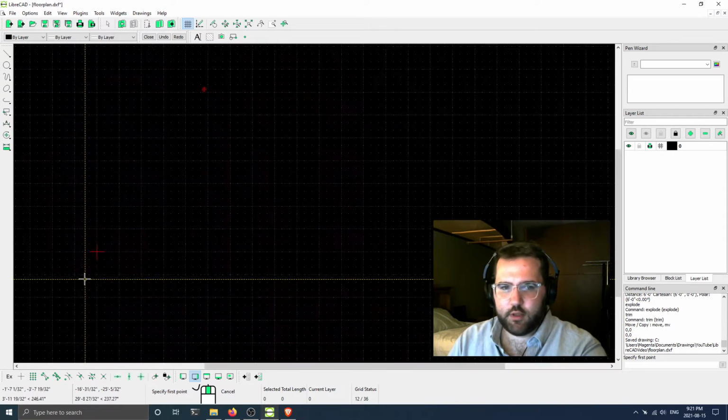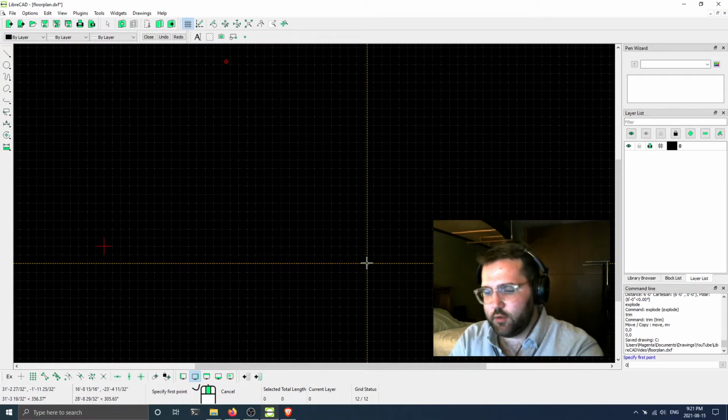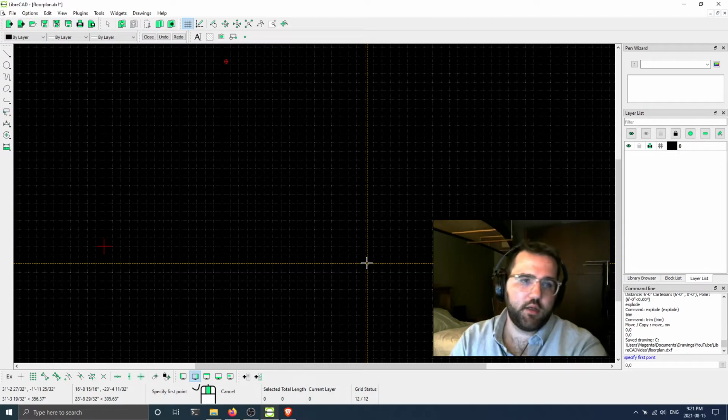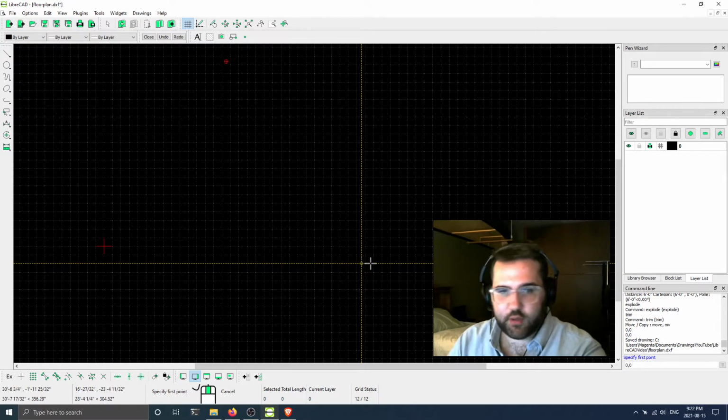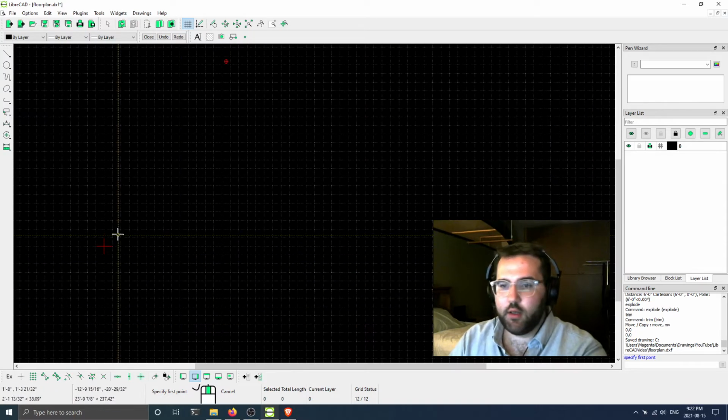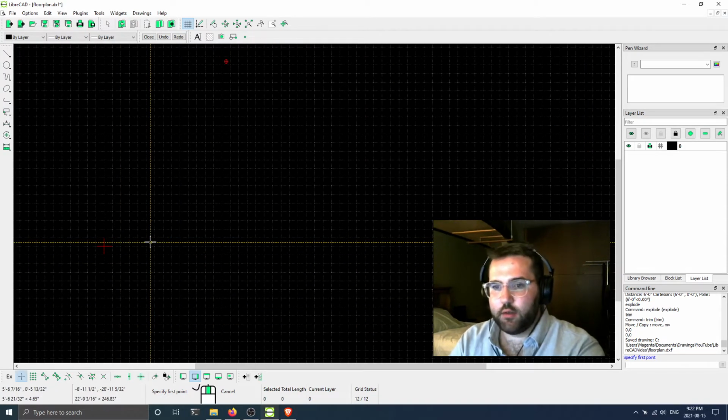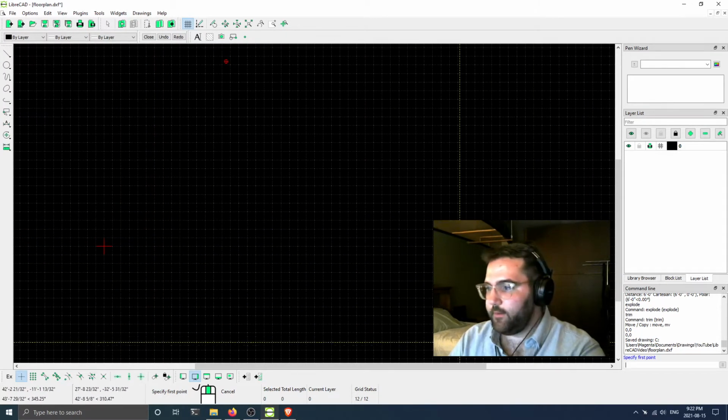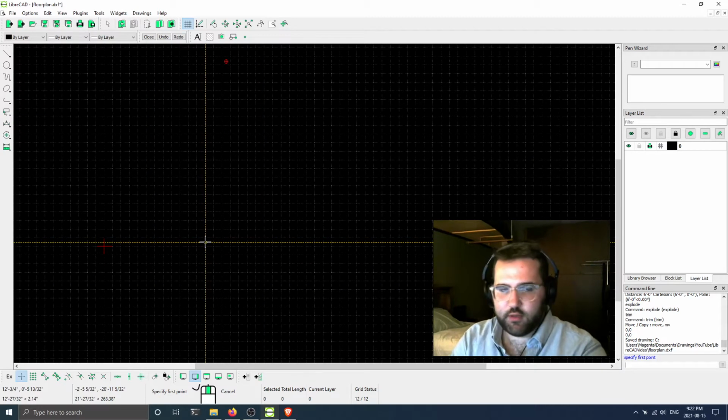There's a couple of ways that you could do that. You could just type 0, 0 on your keyboard, and you can see there that input shown up down in my command line. And if I hit enter, you can see now, sorry, I moved my mouse and it actually removed the input, so keep that in mind if that ever happens to you.